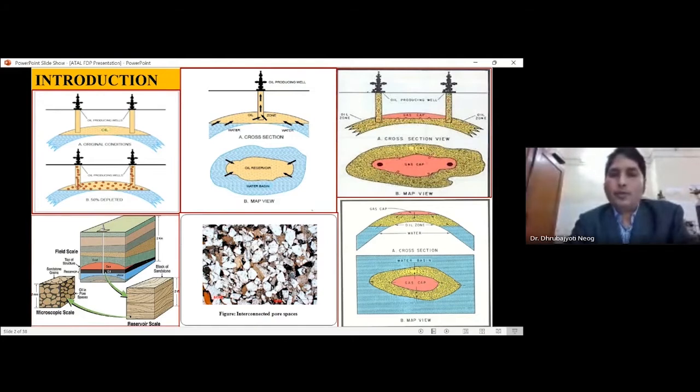Therefore, crude oil recovery from this water drive reservoir is higher than from the solution gas type reservoir, because in the solution gas type reservoir there is no external force to replace the pressure loss with cumulative production of crude oil. The crude oil recovery from the water drive reservoir will be higher than from the solution gas type reservoir.